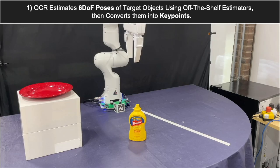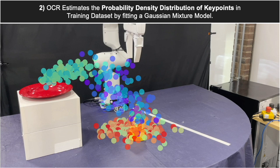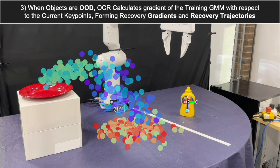Firstly, OCR estimates 6 degrees of freedom poses of target objects using off-the-shelf estimators, then converts these poses into object keypoints. Then, having these object keypoints, OCR estimates the probability density distribution of keypoints in the training data by fitting a Gaussian mixture model. Next, when the objects are out of distribution, which is decided by a probability density threshold, OCR calculates the gradient of the training GMM with respect to the current keypoints, forming the object recovery gradient and the object recovery trajectories.